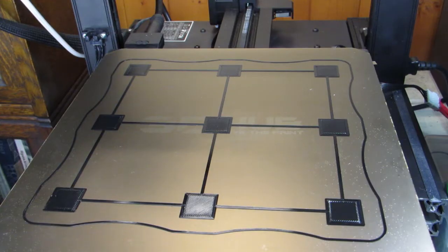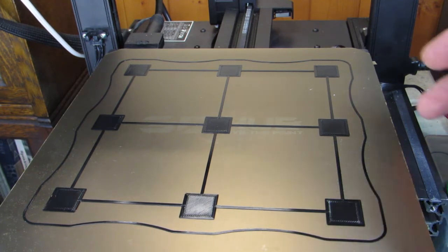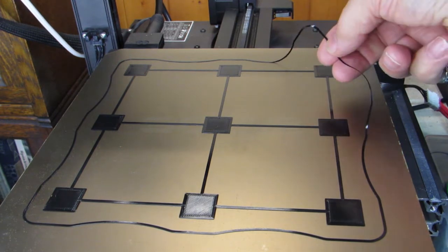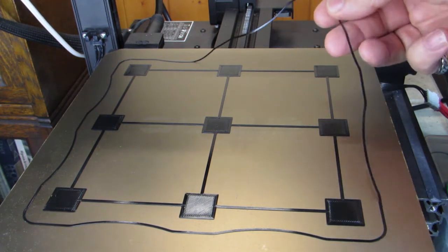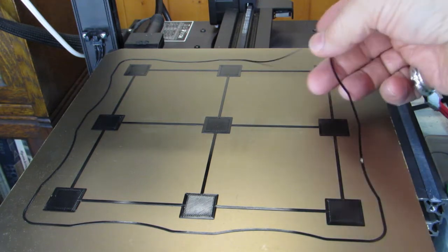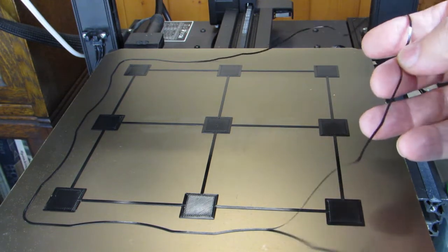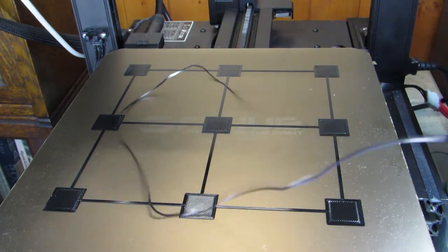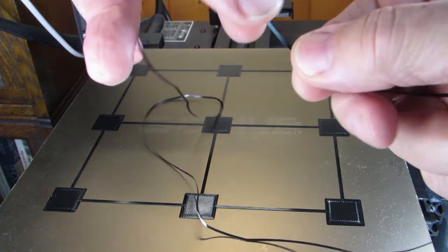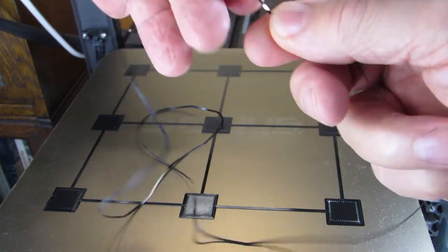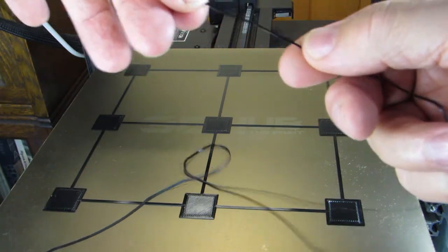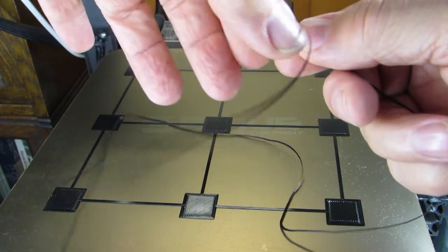Okay, so there's the pattern that we printed. I did mention while I was babbling away that if you peel the skirt first, I've let the bed cool. You see the skirt coming away as a single bonded product and not individual threads. That's our first good sign. You should not be able to push this apart into separate lines. It should all just act as though it's one printed piece, even though it made 3 passes to draw this skirt.